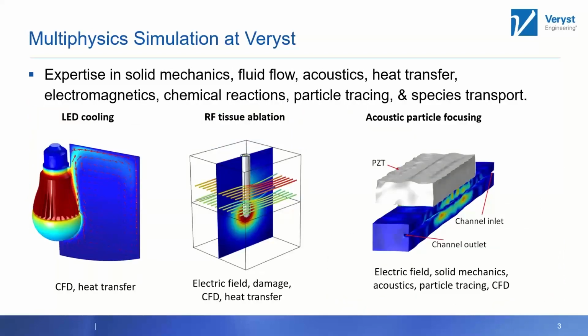I put here three examples from the work that we have done in the multiphysics group of Veryst Engineering. The first one is LED cooling that involves CFD and heat transfer. The one in the middle is RF tissue ablation that involves electric field, tissue damage, CFD and heat transfer. And the one on the right is acoustic particle focusing that involves electric field, solid mechanics, acoustics, particle tracing, and CFD.